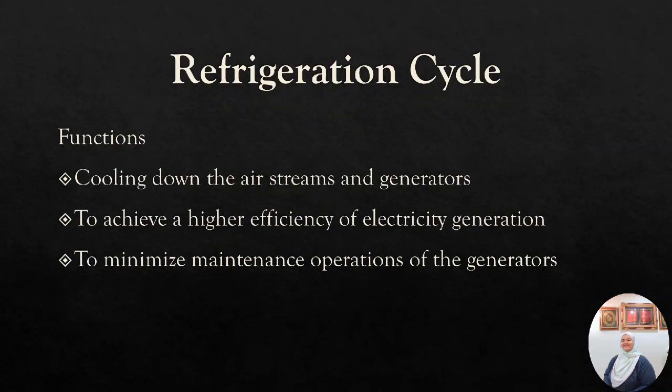The thermodynamic principle that applies in this system is a reverse Carnot cycle. The objective of the reverse Carnot cycle is to use work. The work serves to take the heat from the reservoir and redirect it to the source. And the output of this cycle might be cooling or heating. In this plant, it should be cooling.